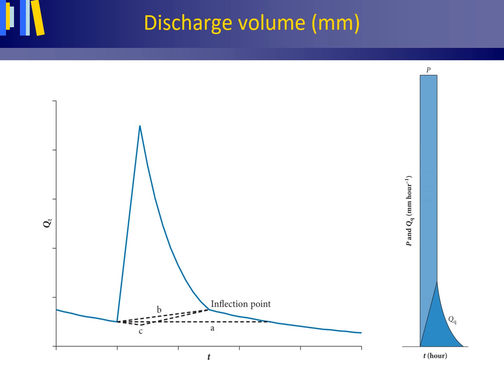One should divide by the total drainage area, irrespective of the fact whether all or only part of the drainage basin actually contributes to the discharge. This is because the same total drainage basin area is involved when translating precipitation or evaporation from volume units to length units or vice versa.